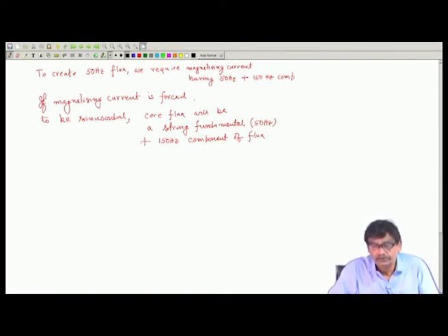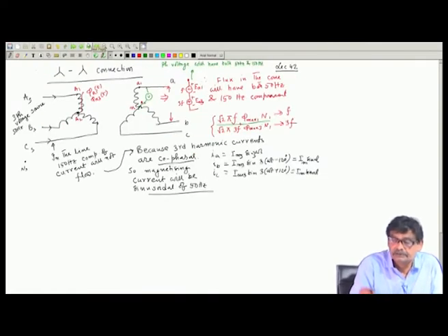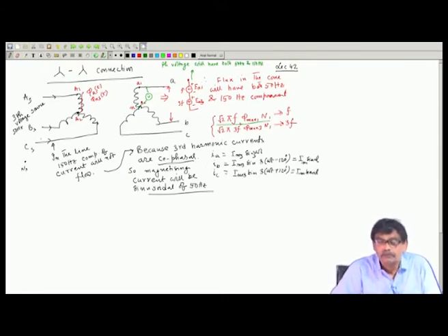Then depending on situations, the current may not have a 150 hertz component, in case of say star connections without neutral connected anywhere. There is no scope for any third harmonic current to exist in the lines of these transformers, and therefore the flux must have a 50 hertz as well as 150 hertz component.